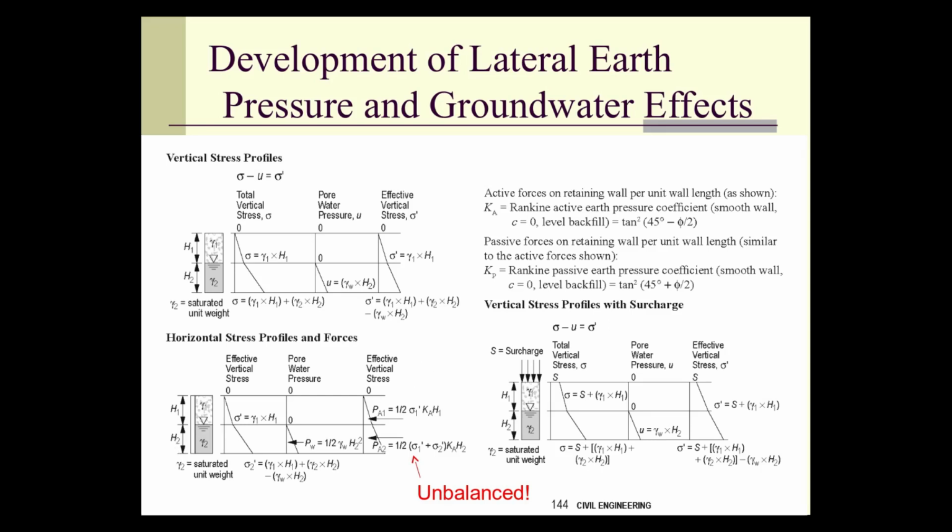Unbalanced hydrostatic forces are very important in many different applications. Tidal, for example, you've got a 3-foot variation in tide. It's unlikely that the water on the soil side is going to drop 3 feet with every tide, particularly on the Atlantic side where you've got high tides twice a day and low tides twice a day, while you only have once a day in the Gulf. It's unlikely it's going to drop, so you're going to have an unbalanced hydrostatic force in that region. And then we talked about drawdown situations, such as with slope stability. We talked about those.